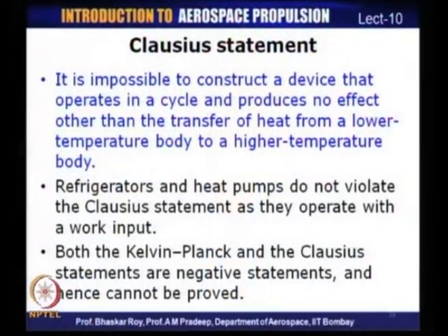So, remember, Kelvin-Planck statement states that you cannot construct a device which can continuously generate a net work output by having simply a heat input, and Clausius statement states you cannot simply transfer energy from low temperature to high temperature without any work input. So, though on paper they look to be entirely different statements, well, that is not really the case. We are going to prove that both of these statements are equivalent, thermodynamically equivalent in some sense.